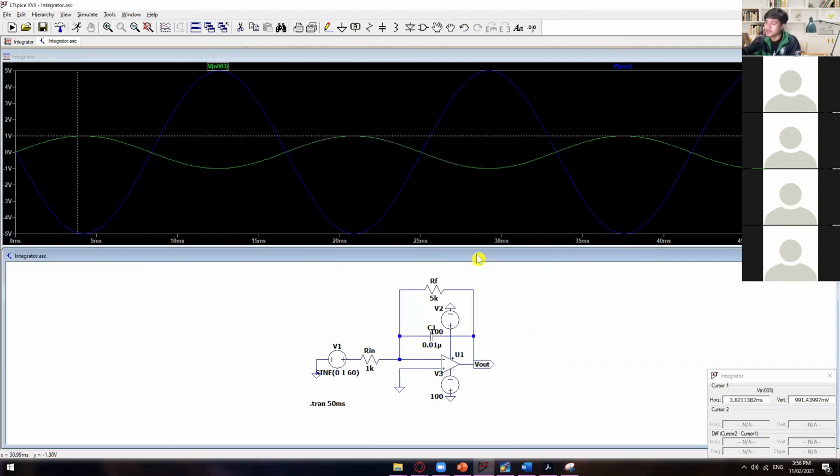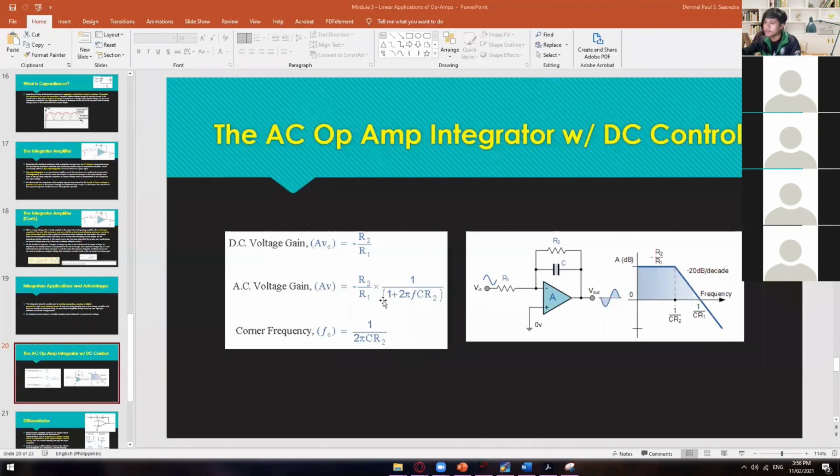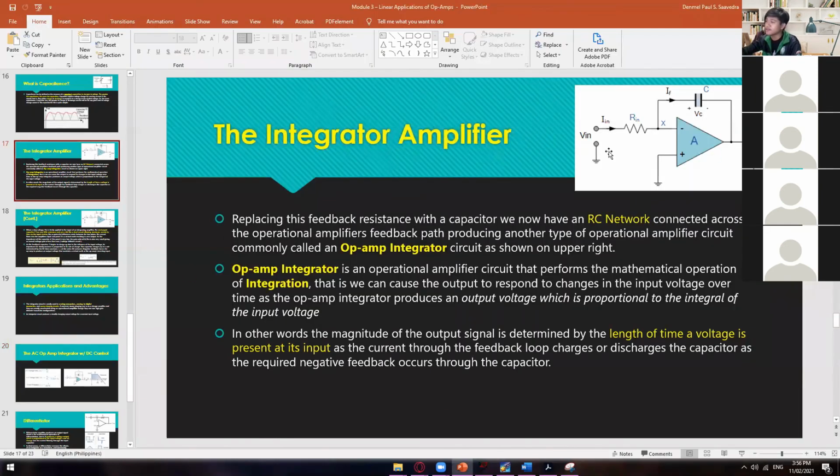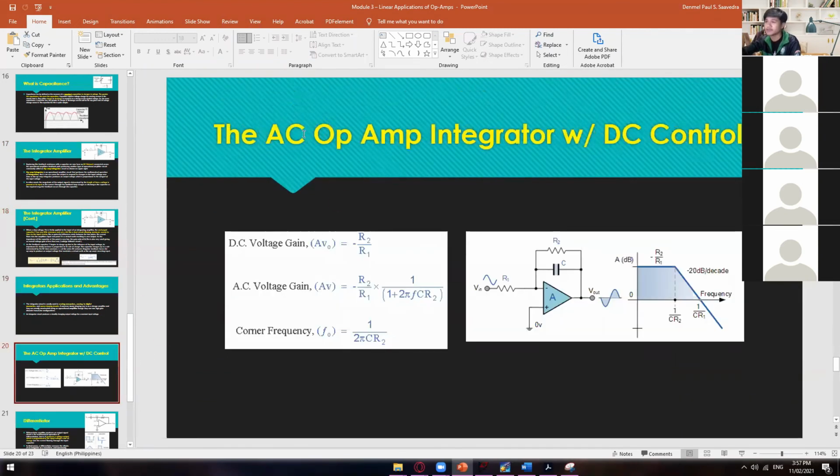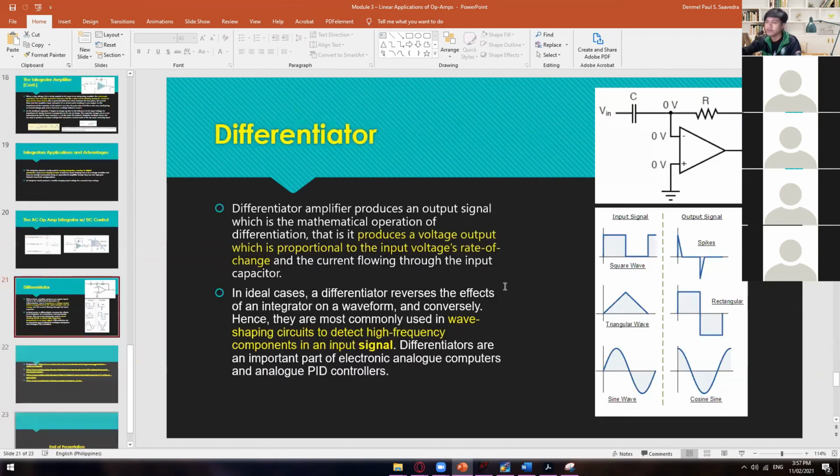All right. So an answer coming from Mr. Eda. So let me just repeat. This one is not a usable circuit since this one's like an open loop when it comes to gain. Okay, it's like 1,000 millions of gains. So instead, we have this kind of integrator, call it the AC op-amp integrator, for us to have more control of your outputs. Right? All right, next.